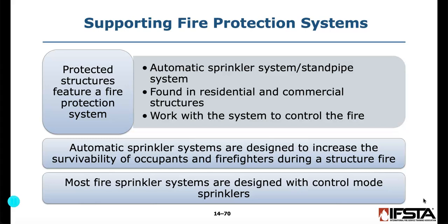So you have fire in an apartment, one apartment. That apartment's got maybe 2 sprinkler heads in there. Depending on the size of it, you're not going to get every single apartment building activated. The smoke or the heat will go to the alarm or the detection device. The detection device will alert that there's smoke or fire. Then whatever mechanism holding that sprinkler together will release, and then it will cause water to flow in that area.